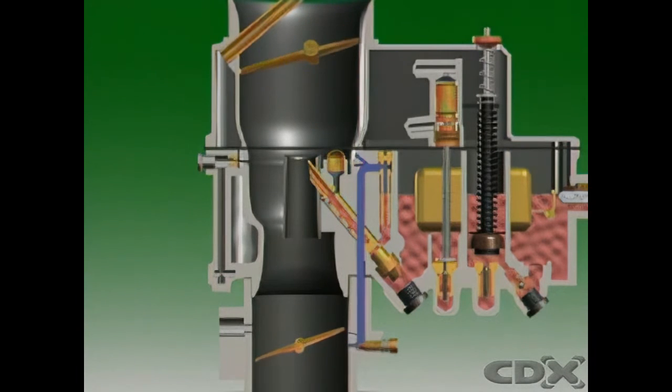Closing the choke valve closes the carburetor intake. The pumping action of the pistons creates a low pressure area below the valve even without venturi action. This low pressure causes fuel to flow from the discharge nozzle and from the idle and low speed ports, and provides the rich mixture needed to start the cold engine.